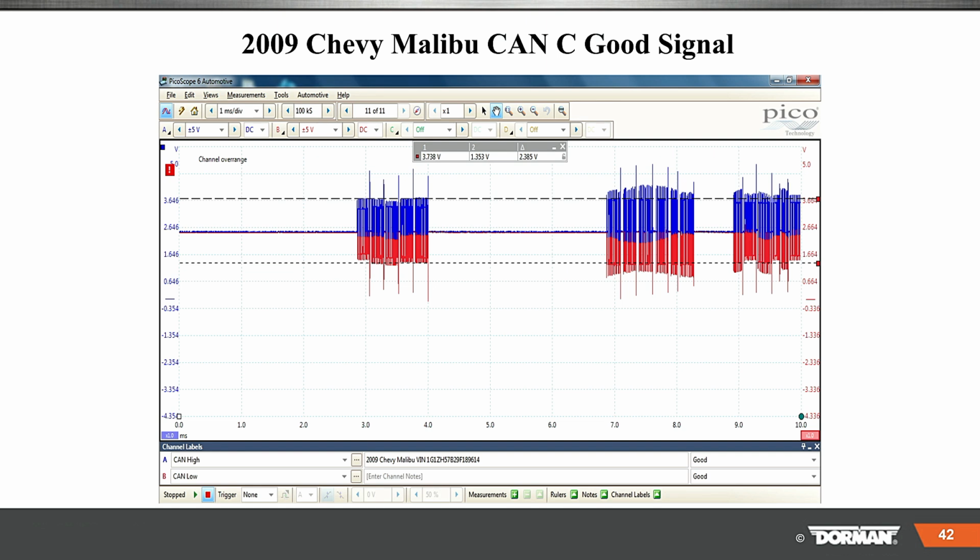Floating ground allows for accurate ground on all loaded circuits. Yeah, so let's talk about that floated ground again. A floated ground, when you crank the car over, we all know 12 volts is going to go down to 10 volts or so, right? Maybe, if you've got a really good system, just into the 11 range. But we're pulling on the ground, the chassis ground, right? We don't want something that has to be so accurate being pulled on. So what do they do? They raise the level.